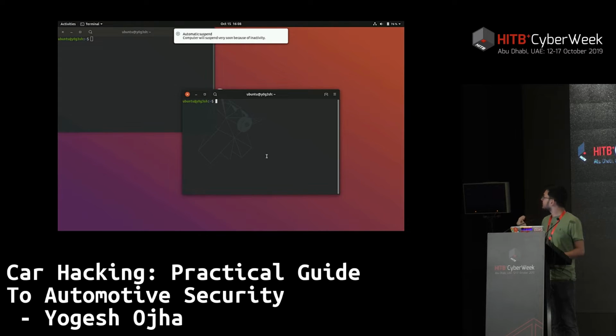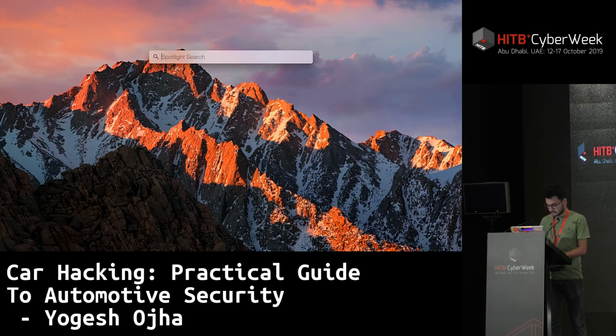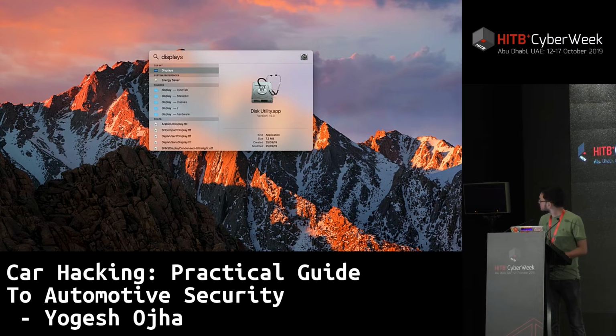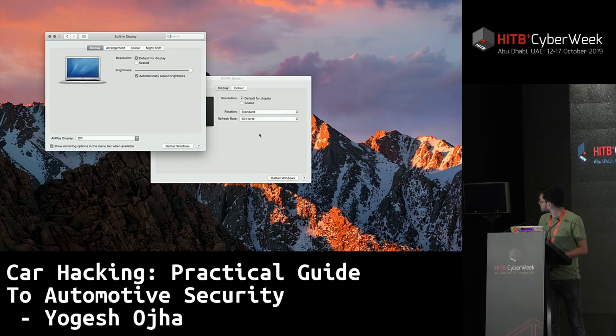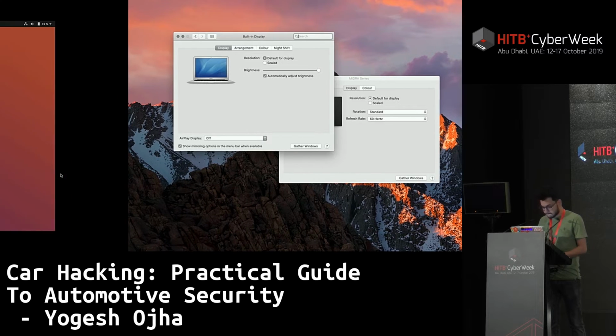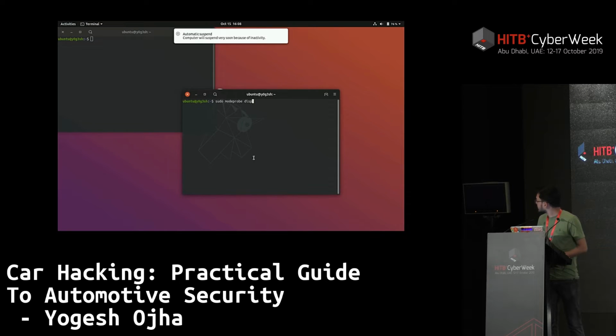Right now, since we do not have any virtual CAN interface, what we can do is load the kernel modules for CAN, and then the same thing for virtual CAN as well.